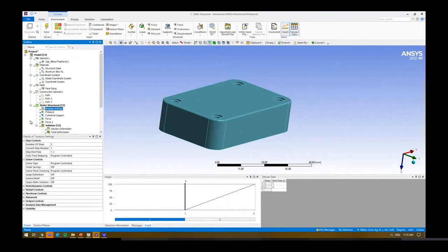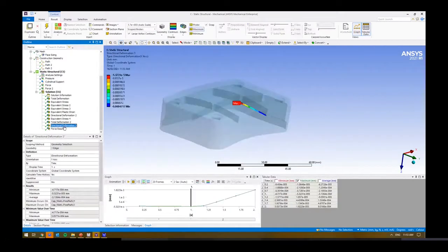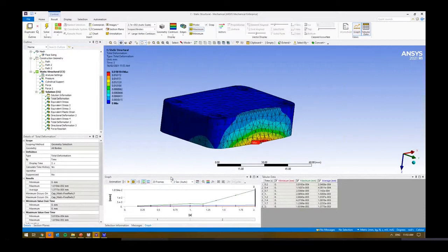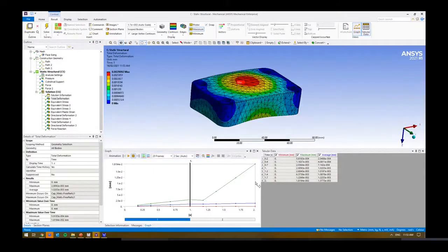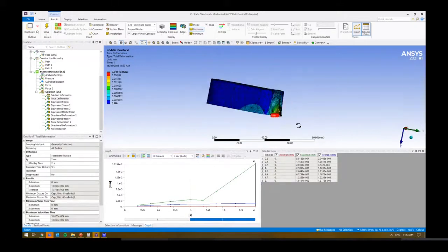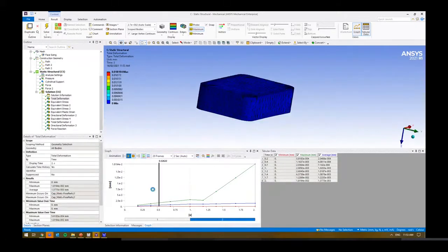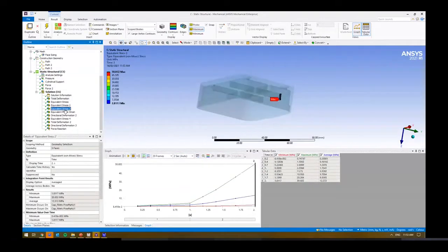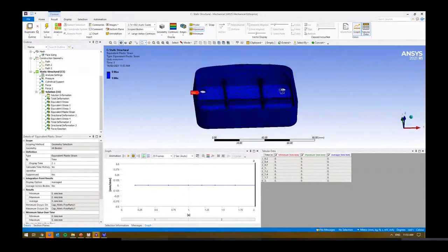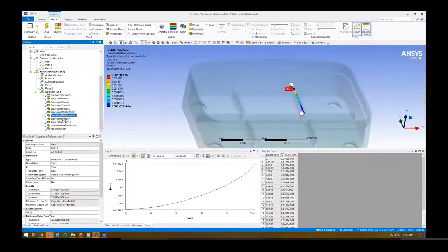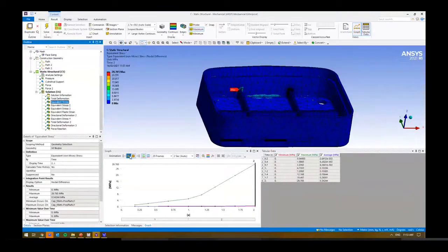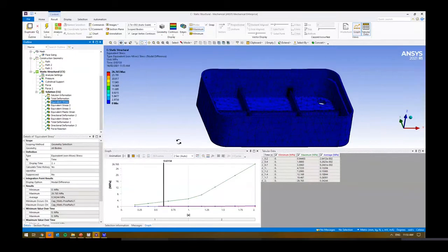I think some of the things that we haven't gone into too much detail about is in some of the sub-steppings. So if we just have a quick look, by the way, we'll notice that in the first step, we've got force that gets pushed up. And then towards the end, we've got a force that's pulling it out. Right, so we're applying both up and then it's coming out. Right, and then again, you can look at things like your plastic strains and see what's happening around some of those regions. So it doesn't look like we've got any plastic strain whatsoever. And we can also have a look at the stress around some of these regions as well. All right, so it's around 20, so there's not a huge amount in this particular case.